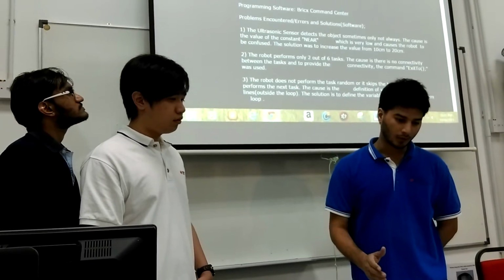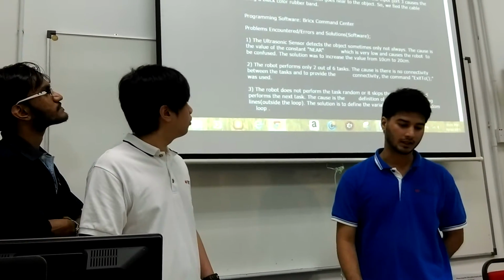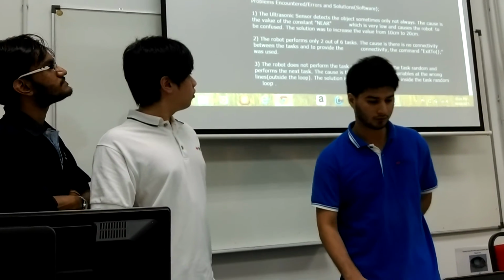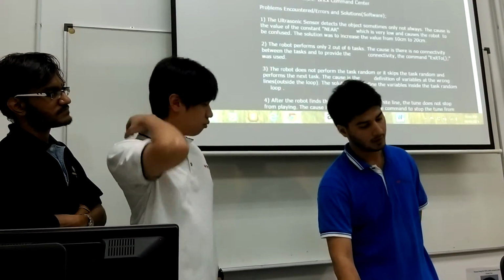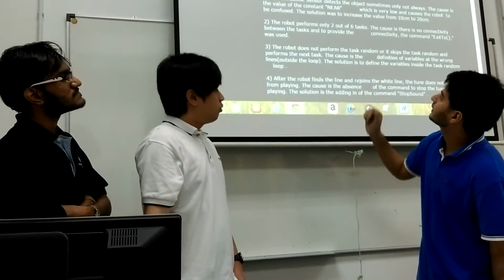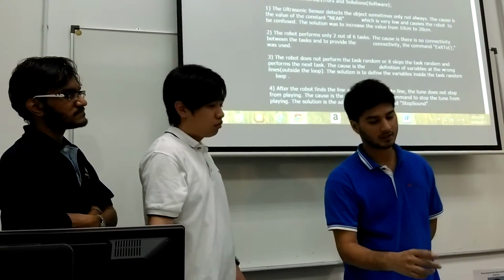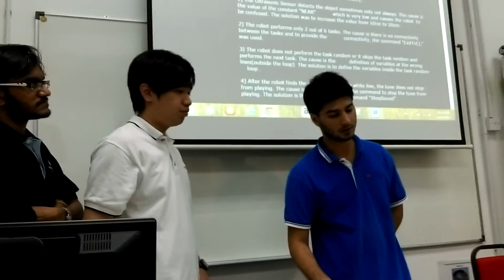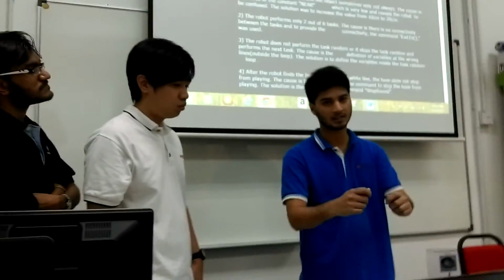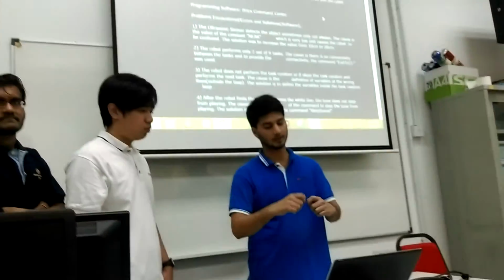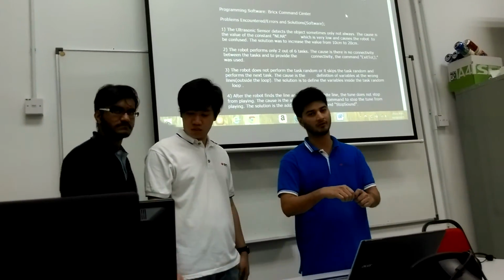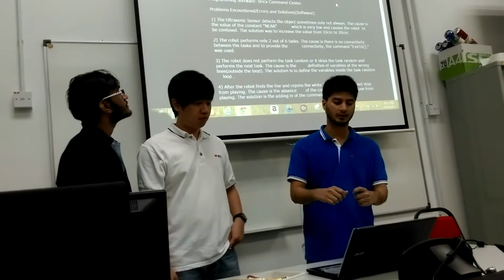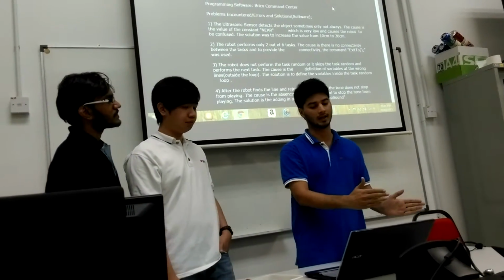No problems were encountered during the assembly of hardware parts, along the long time that we searched for the parts that we were building, or when we were building our demo board. The second part is the twisted wires for connecting the light sensors and input port 3 causes the objects to fall sometimes because the wires are too long. So we use rubber bands to tie the wires so that they don't affect the sensors and everything, so that it will move along the line.